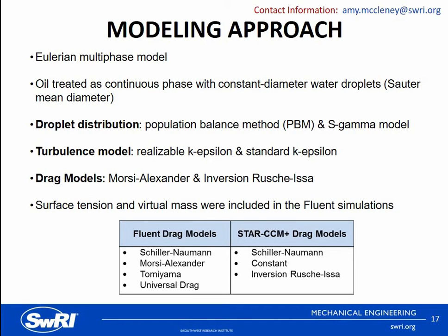In this case, the overall separation efficiency was within 1.5% of the measured experimental value. In STAR-CCM+, the Ishii-Zuber drag model performed the best of all three choices. The separation efficiency was within 2% of the measured value. It is noted that this drag model is promoted in STAR-CCM+ as having a built-in pseudo-emulsion model based on empirical correlations from experiments.